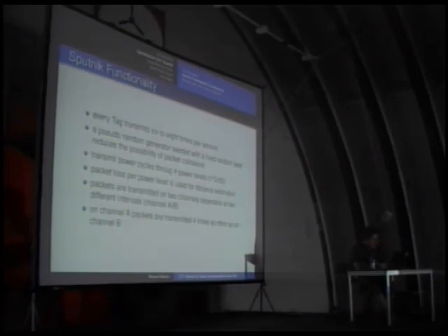Yeah, and to make sure that if we have areas where the tag density is too high, we don't get a denial of service attack, we have 2 channels. On one channel, you have a low frequency tag transmitting, and on the other channel, high frequency. So if we get too many sightings in a given area, then we just turn to the second channel, where we get much fewer beacons per second. Currently, it transmits on channel A 4 times as often as on channel B.